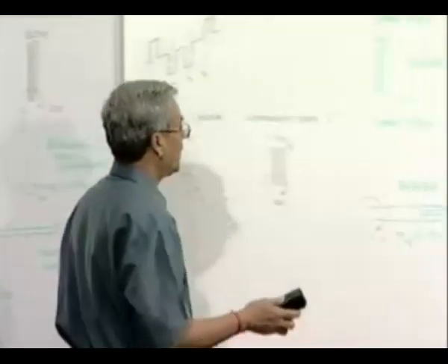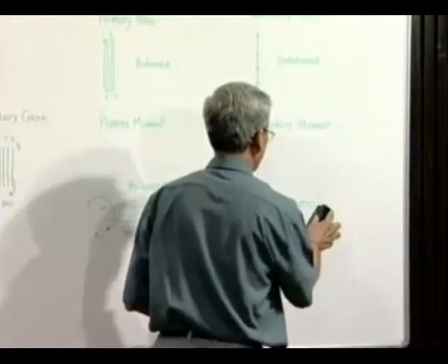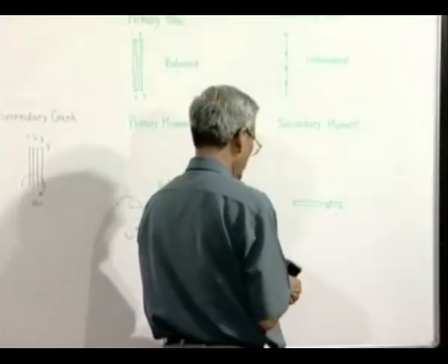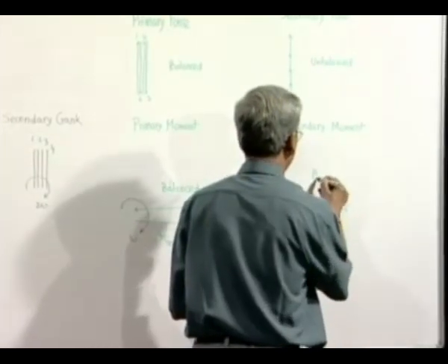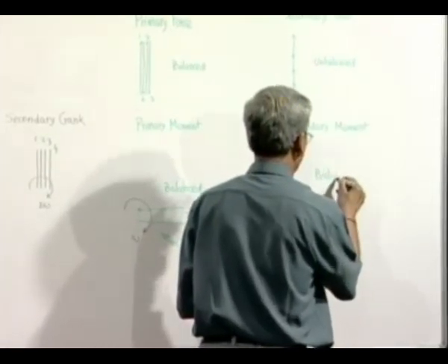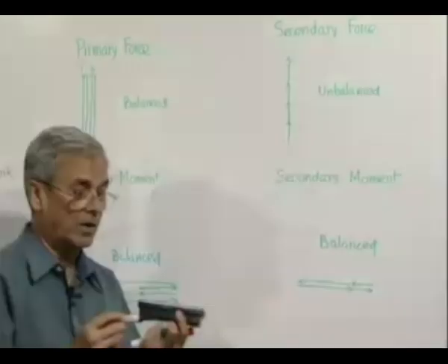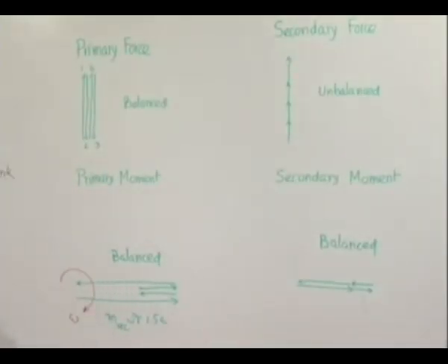So, overall there is an improvement, because earlier the secondary forces were unbalanced and primary moment was unbalanced. Just by changing the firing order, we have achieved total primary balance and only the secondary force unbalance. So, now I think this sends the message that firing order is very important.